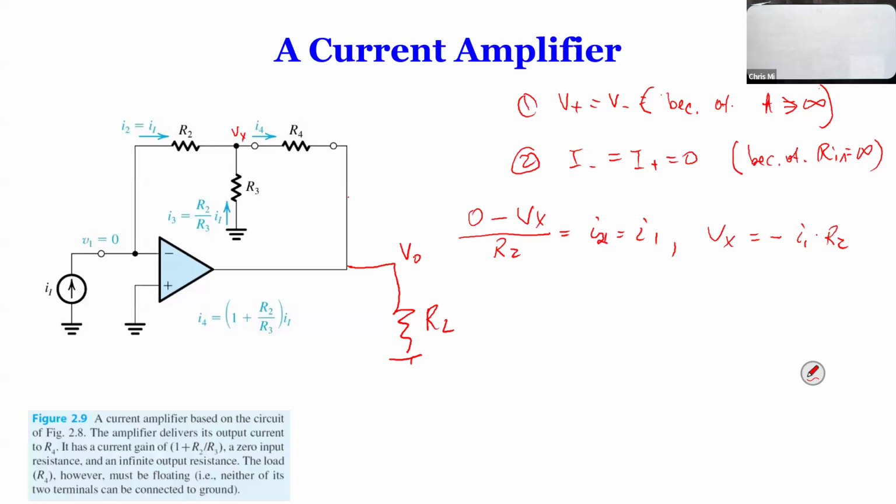Since the voltage at the output has nothing to do with this, once you find the voltage here, you can use the voltage divided by the load resistance to get the current. Because it has nothing to do with the output, typically you see a lot of the analysis doesn't have an output; it simply has the output node over there.